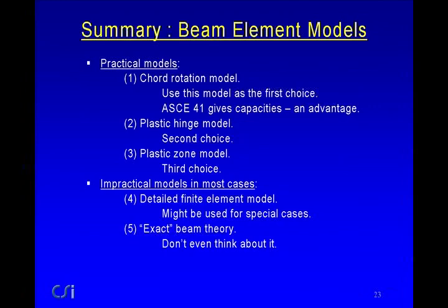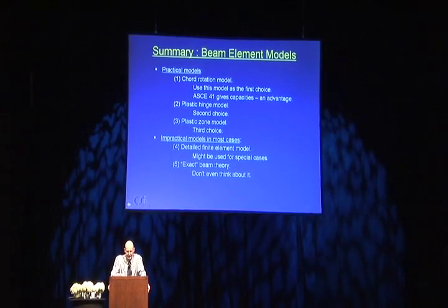If that doesn't work, use a plastic hinge model. If that doesn't work, use a plastic zone model. If it doesn't work, you might consider a detailed finite element model, but I don't think you'd ever consider using exact beam theory.